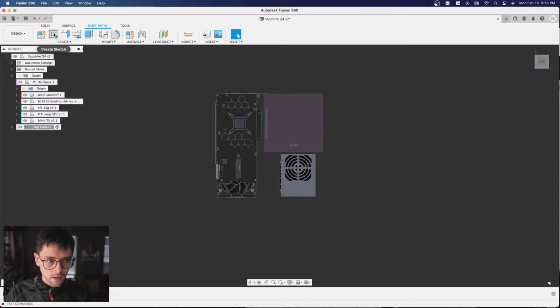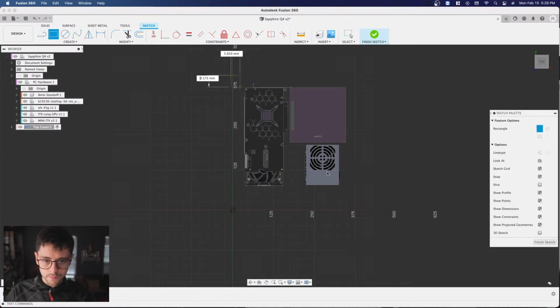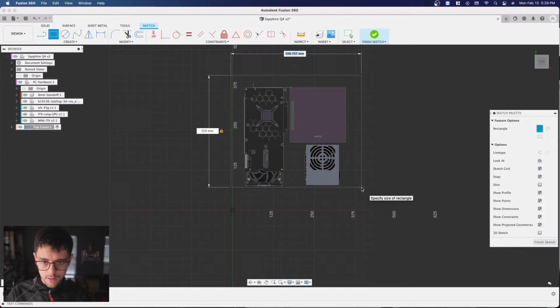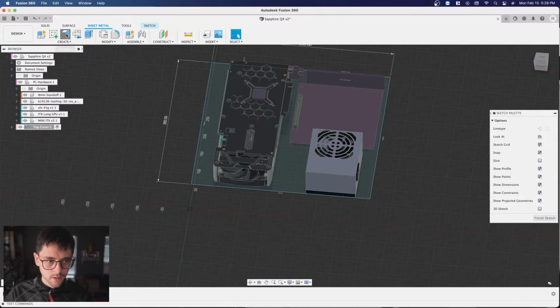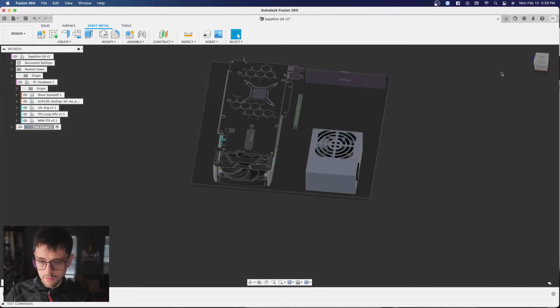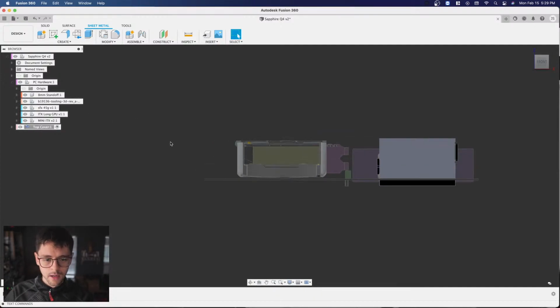That's activated. So I'm going to create the sketch, click outside my workspace. Make this 350, make this 360. And I'm going to make my flange. Okay, we're back to where we were, but this time I have my own little component in the bottom, or I don't know if you can see this on the left side, the top cover. It's going to keep my design history nice and neat here and not break anything else as I'm moving between components. So I want that all separate.